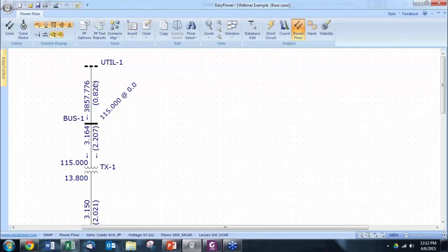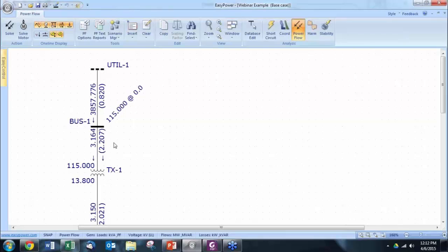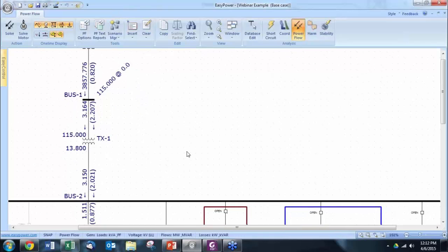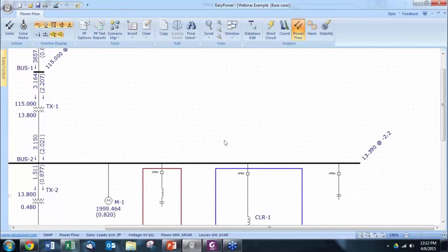With a 0.82 power factor, you are looking at a fine of around 7–8% of your total billing. It's very expensive. So this is an urgent problem that we need to correct, and therefore an engineer is commissioned that says, fix this problem. Okay, so now I need to reverse or to neutralize this reactive power flow. So the solution might be pretty easy, and then you say, okay, I'm going to install a capacitor bank.